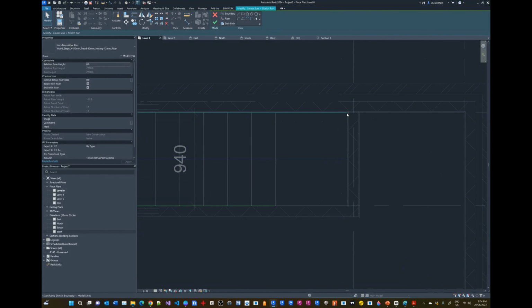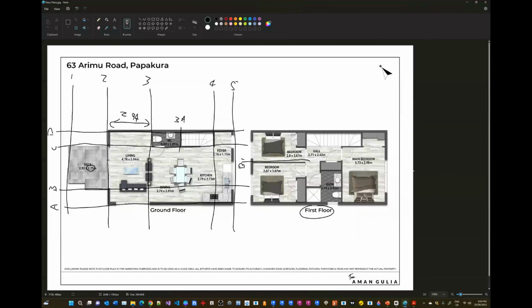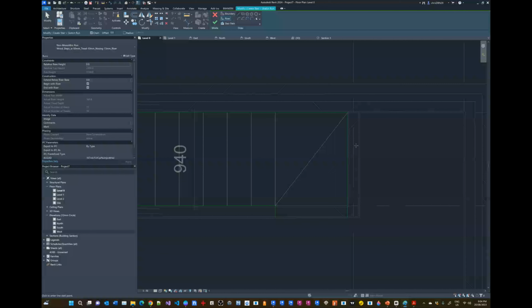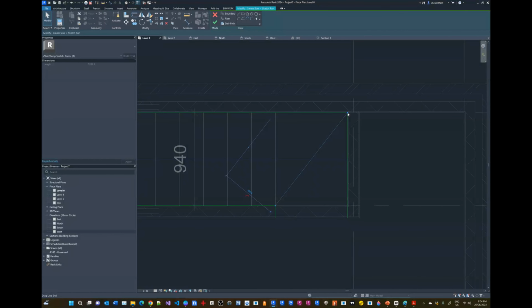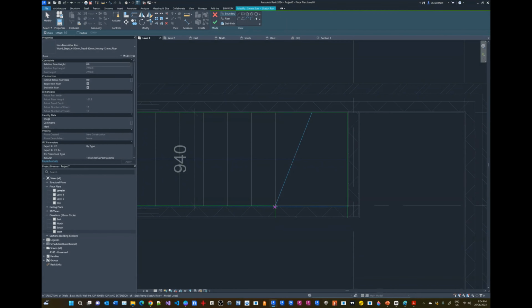All right, now that we've got this done, we're going to continue to create the boundary. So we're going to say, okay, this staircase actually is going to run down to here. Also, it's going to come out on this side to that end. We're then going to go to risers, and we're going to say, let's create a riser that splits here, right? Just like we see there. Oh, I see it. Actually, there's 1, 2, 3 steps. Okay, so this actually is going to sit somewhere here. And we're going to have another riser that sits here. Okay. And then finally, there's going to be a riser at the end.